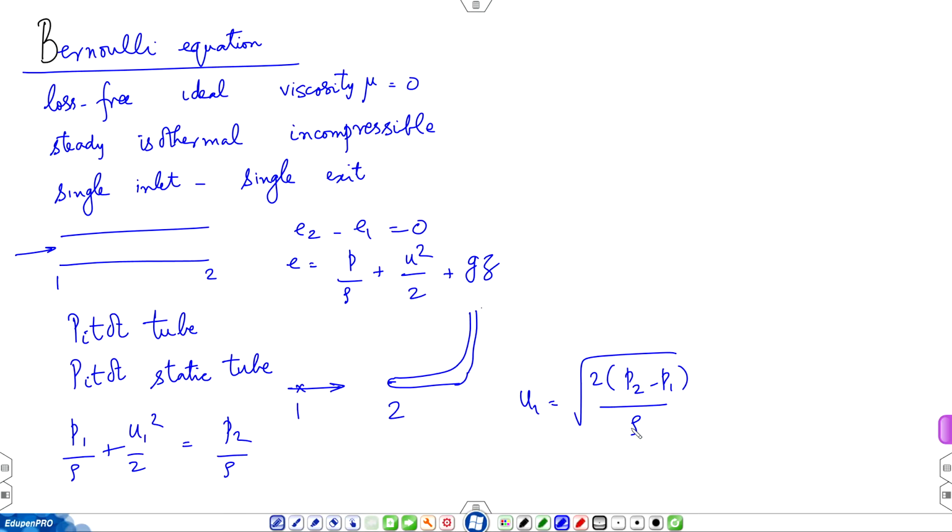So, this pitot tube usually will have a very narrow, small diameter hole through which pressure P2 is communicated. This hole does not affect the pressure at point 2, hopefully. I will show a U tube here which measures P2 minus P1. P2 is greater than P1. So, the liquid level, so this is point 2, this is point 1.